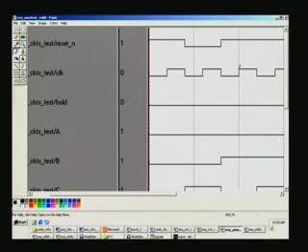So this is the line, right? Although that is combinational logic as such, now this is in synchronous mode. So any register will always be a synchronous type, and it will happen only during the positive clock edge transition. And that's how you have set the pixel out P here.